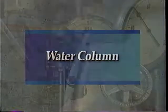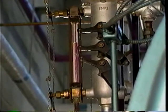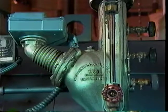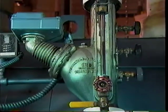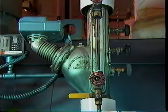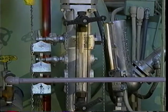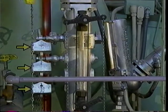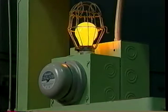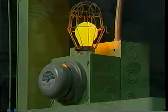Water column. The water column minimizes water turbulence in the gauge glass to provide accurate water level readings. Water columns are located at the NOWL, with the lowest part of the water column positioned at least 3 inches above the heating surface. Water columns for high-pressure boilers consist of the main column and 3 tricocks. High and low water alarms or whistles may be attached to the top and bottom tricocks.